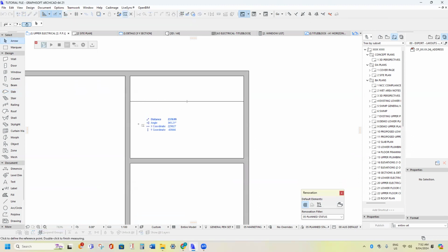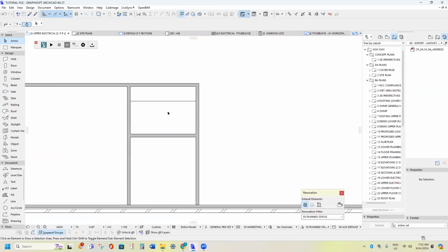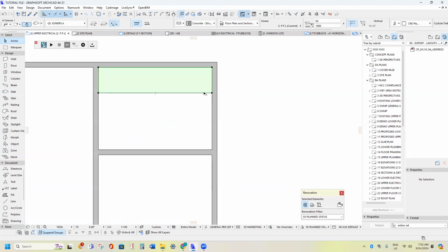And if you click the M button, you can measure from there to there. That's 1 meter. You've got plenty of walkway space in there. Now, if you want to extend this shelf to come around as an L shape, you'd click on the joinery on the slab tool, then click on the corner, the black dot. Then it brings some options up here. You want to press the plus button, and that's going to mean you're adding to it. And then you click and drag down to the corner, click, come out, press R, 450.